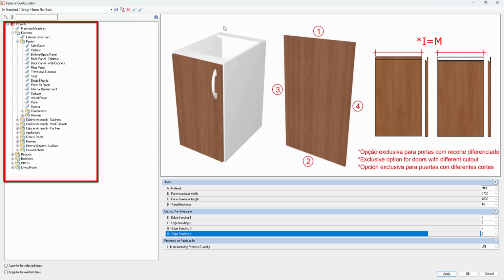This comes handy when you start using Promob's cutting program, because it'll automatically allow for the 2mm edging, and your cut size of your door will be 2mm less, obviously, all the way around. You don't have to manually calculate it, it does it all automatically for you.